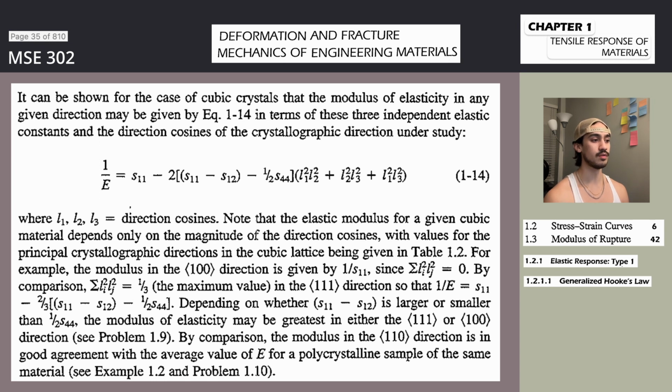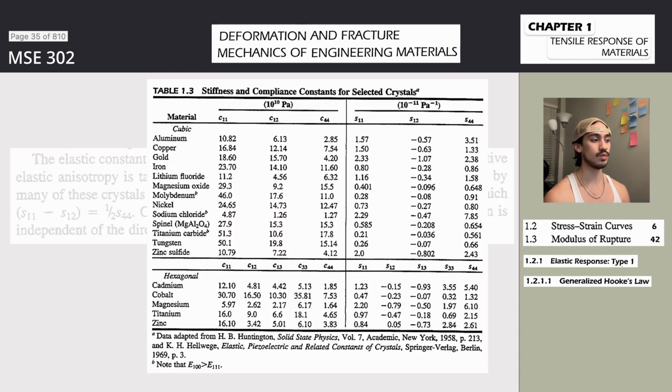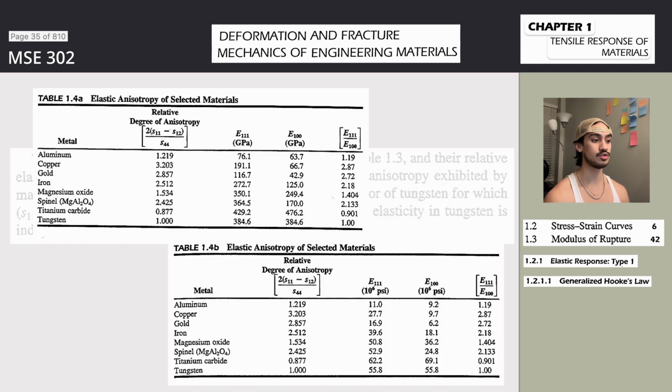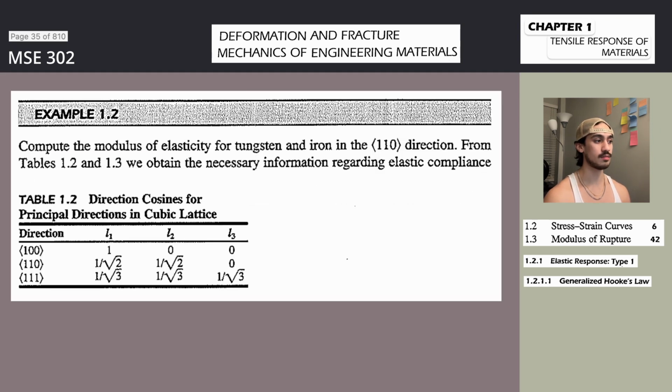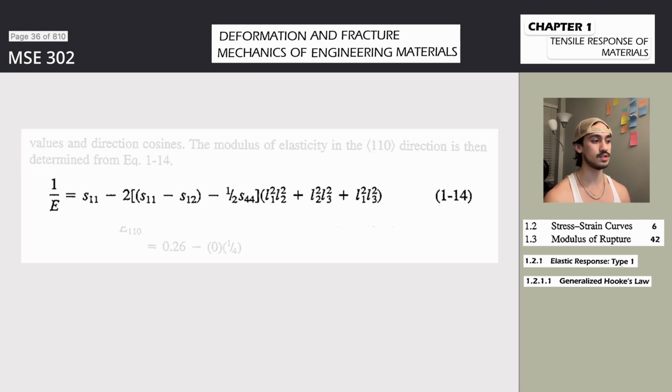To arrive at a uniformly accepted method for determination of the yield strength, therefore, a standard test procedure, an ASTM standard, has been adopted. The yield strength value is obtained in the following manner. 1. Determine the engineering stress-strain curve, such as the one in Figure 1.6. 2. Construct a line parallel to the elastic portion of the stress-strain curve, the sigma-epsilon curve, but offset from the origin by a certain amount. The generally accepted offset is 0.002, or 0.2% strain. And 3. Define the yield strength at the intersection of the stress-strain curve and the offset line. As cited above, this value is usually defined as the 0.2% offset yield strength.